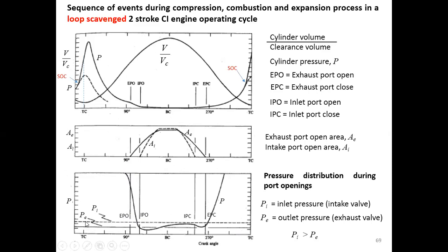So if you know that the outside pressure is this, then you know why the exhaust port has to be open right here. Because at this point, the pressure inside the chamber is still higher than the outside, right? So the exhaust gas inside can easily flow out, right, as along the way the pressure starts decreasing. So the exhaust port opens first because of this, okay?